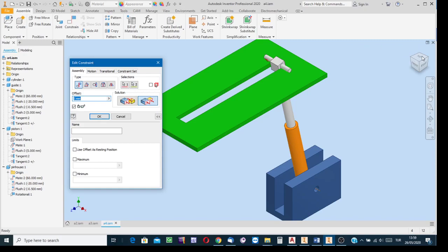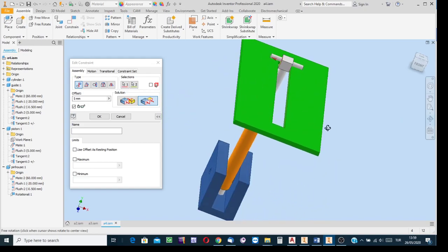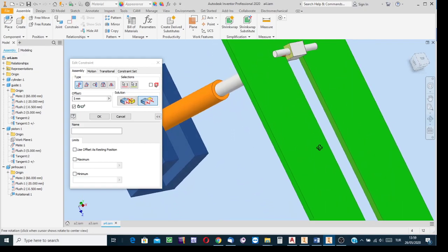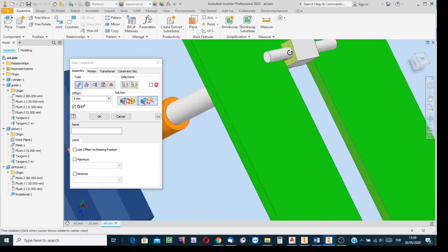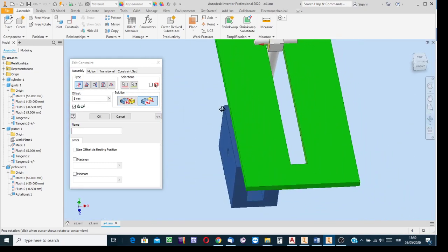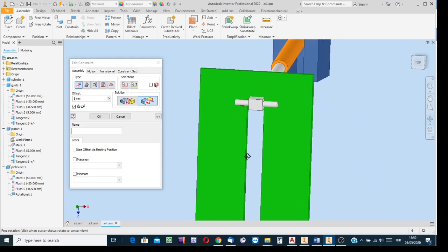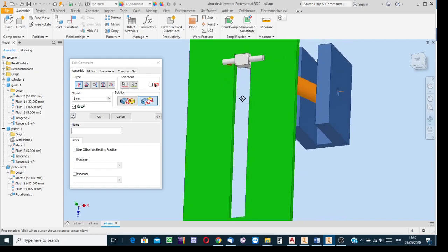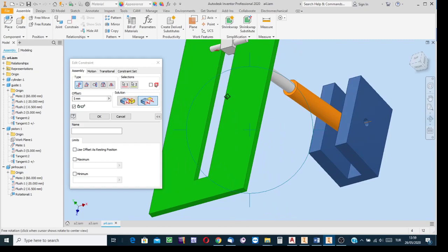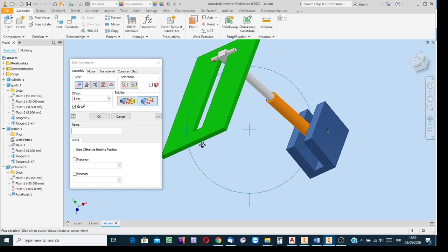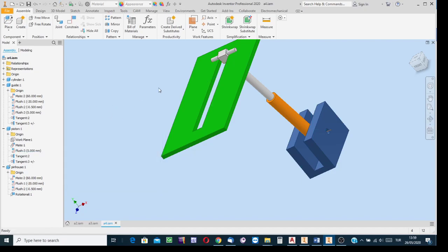The distance, well, try to rotate it, between this surface of the channel and that highlighted surface of the piston end is 5 millimeters. Okay, between the side surface of the piston end and the side surface of the channel there's a clearance of 5 millimeters. I said that these are always parallel in positioning.